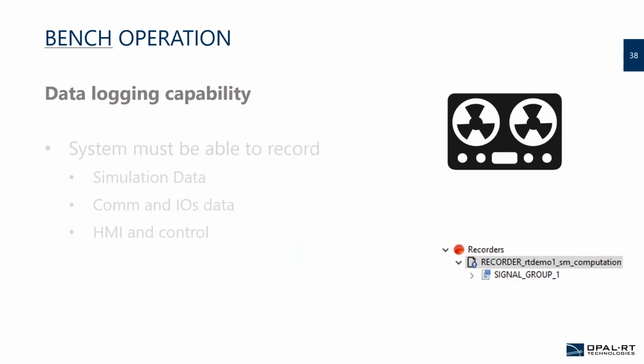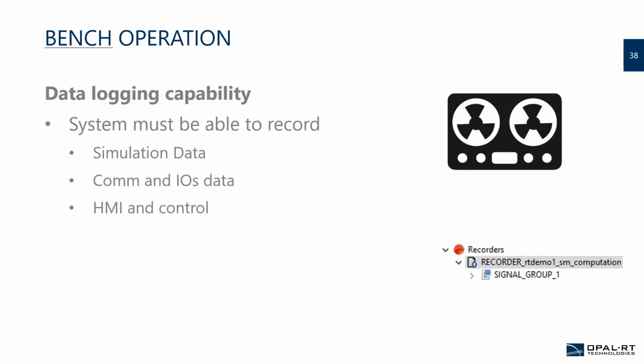If we go into the data logging capabilities, having the recording function is for sure mandatory on all test benches, because you want to monitor a lot of different signals, and if something happens, like a fault coming from the ECU, you want to see the sequence of what is going on. So you really want to be able to record all the simulation data, the virtual data, everything that's going on the COM and the IOs as well, and all the commands, special commands, everything that's going on the HMI.